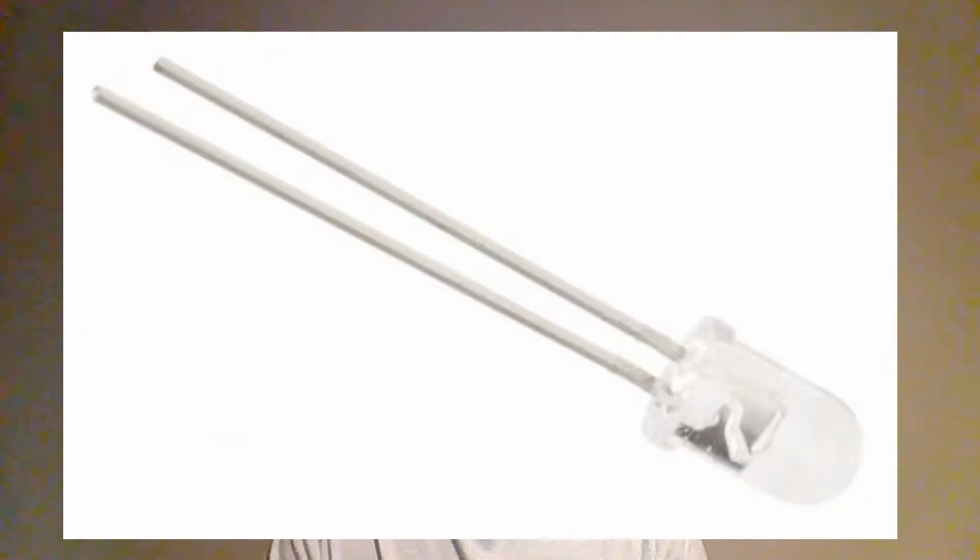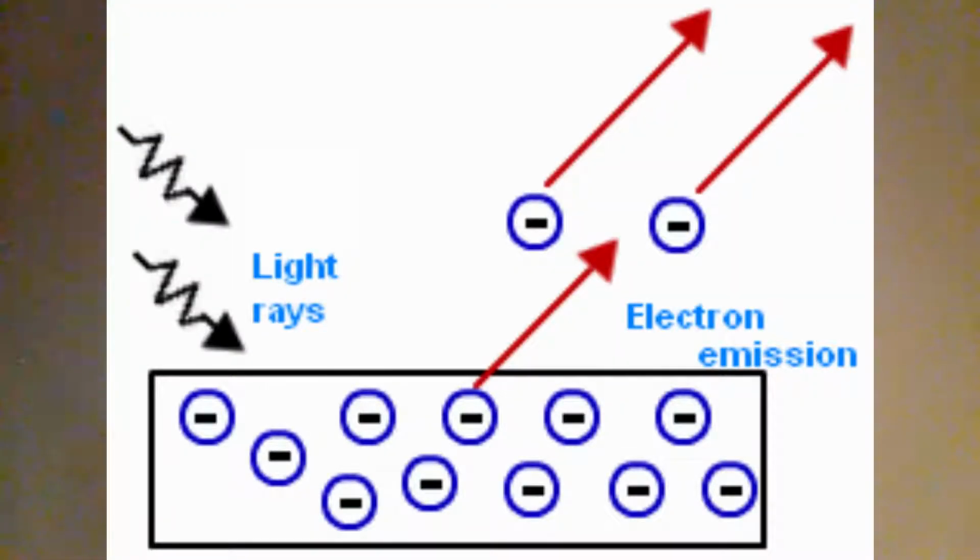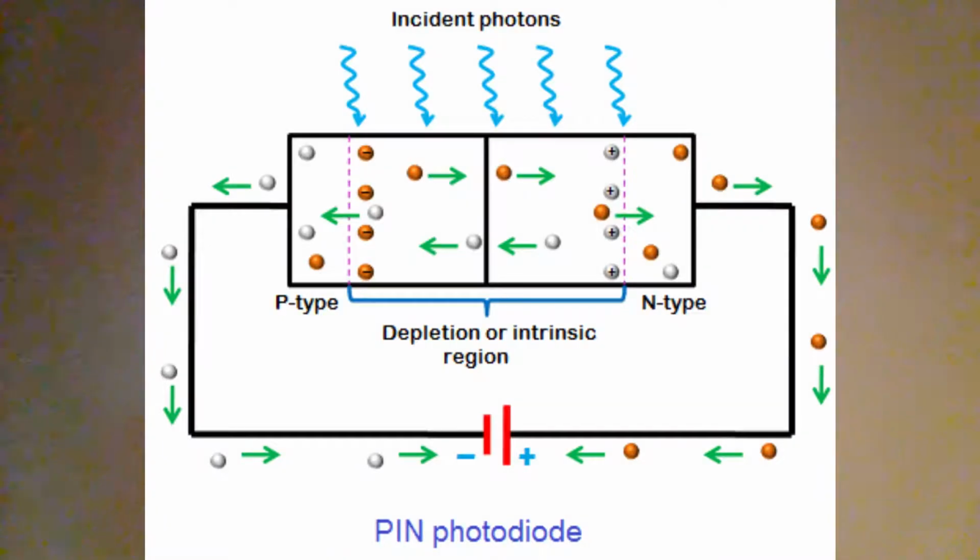In our system, we use two different sensors, one of which includes a photodiode. A photodiode works by converting light which hits the diode into an electrical current that could be used for calculation. The electrical current is produced when a photon hits the diode, resulting in an electron hole and a free electron. This is also known as the photoelectric effect. The electron moves towards the cathode and the electron hole moves towards the anode, resulting in a current. More light equals a higher current.